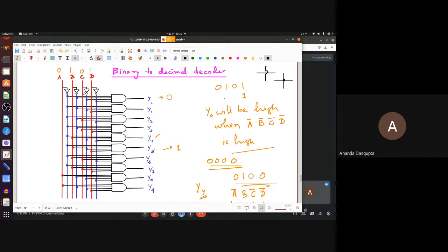That's simply because in digital circuits there are way too many wires. And if you had to show a bump every time two wires crossed, then things would become very, very messy indeed. The standard convention in digital circuits is if you don't show a connection, then there is no connection. Two wires which just cross each other without a junction shown are not joined. Okay, so that's the convention for digital circuits. That's the one we are going to follow here, at least.